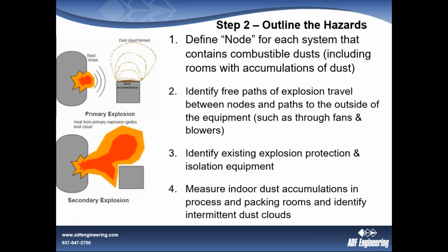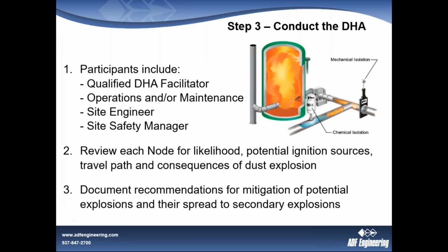Different standards quote different levels of allowable dust accumulation, so this gets very inconsistent and very confusing. Some standards will say 1/8 of an inch, other standards will say 1/32 of an inch, and another standard yet says enough dust to obscure the color of the floor. So it really doesn't take much to reach this point. And they'll also point to things like 5% of the area of the room.